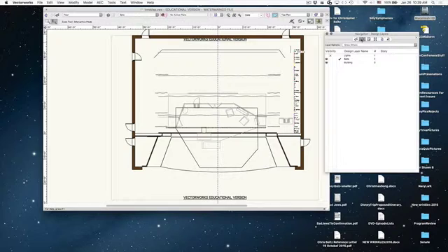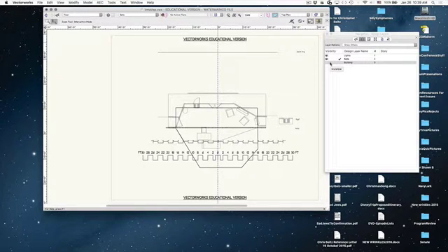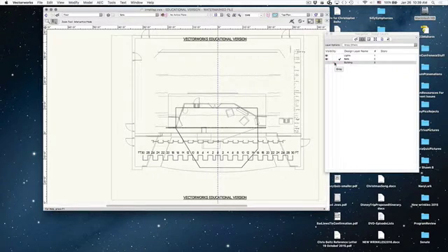Okay, I work with very few layers. Layers I use as big picture items. I have the scenery layer, the building layer, and the lights layer. For this class, you guys will probably do most of your drawing on which layer? Lights. Okay, so this means I can also grab everything. So I'm going to turn the lights on at the moment. There's a couple things in there. But I can turn the building off if I want to. Okay, building's in my way. It's confusing me. I'm turning it off. Okay, or it can be back on. Okay, or it can be gray.